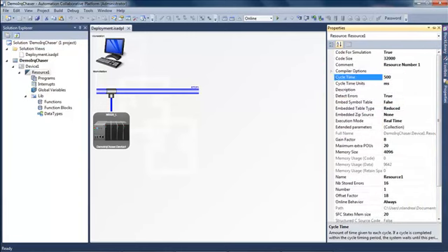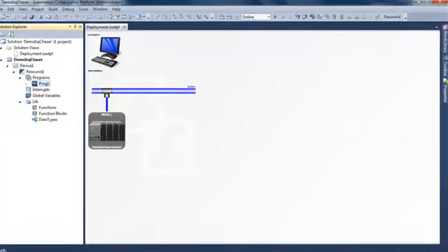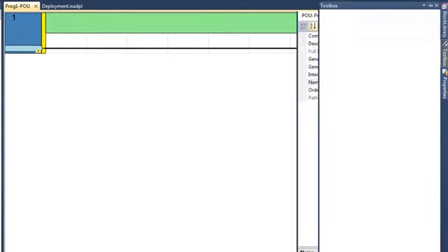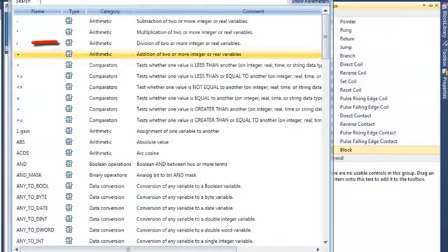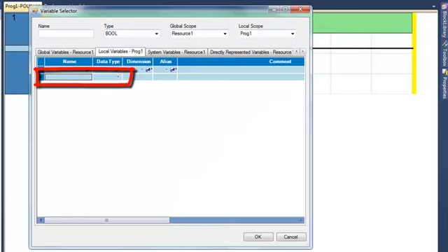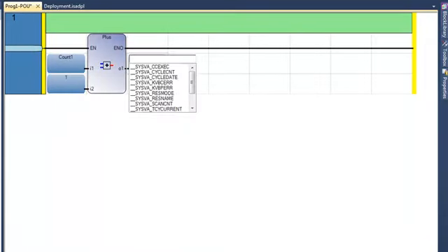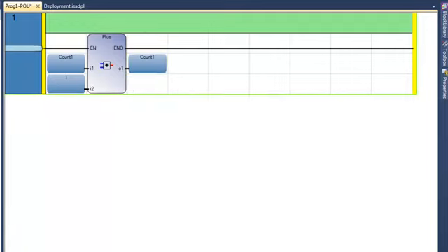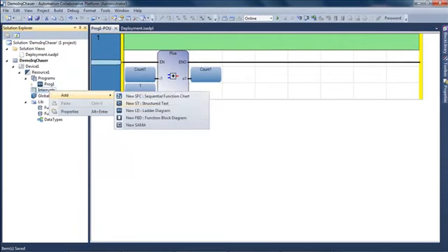So I'm setting a cycle time of 500 millisec for my cycle, and I create in ladder a new program which will just increase a counter. So I create an addition. I will create a count1 variable which is a double integer. So I choose the int, I increase with 1 and I put the result in the same variable. So this program will be executed each 500 milliseconds.